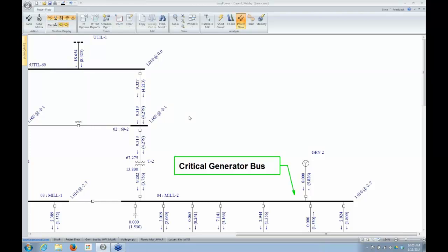And then as far as power factor savings with power factor correction, from your power factor penalties perspective, as long as the capacitor is on your side of the meter, that's all the utility cares about. You may have some preferences as to where you put them because of other constraints like the harmonics.